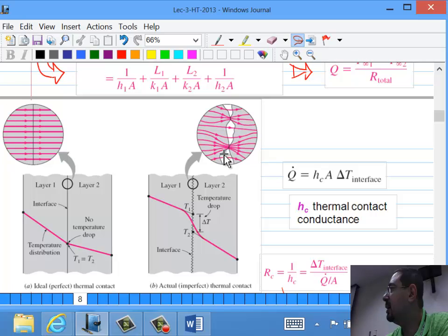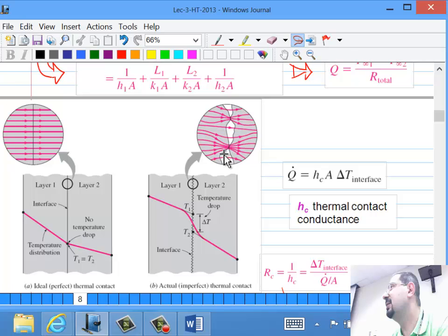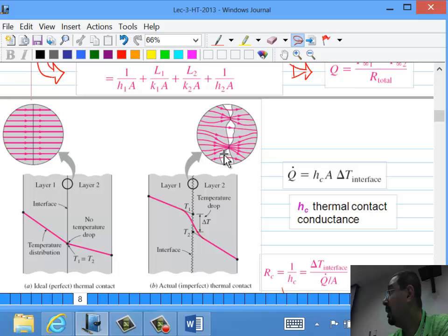Right? Sometimes you do it on purpose, so that if you want to do a good job insulating your house, you basically put all those layers of insulation, right? So that you wouldn't have that much heat transfer. And so if you trap some air between them, that's a good job actually, from the heat transfer point of view. Air is not really conducting that well, right?